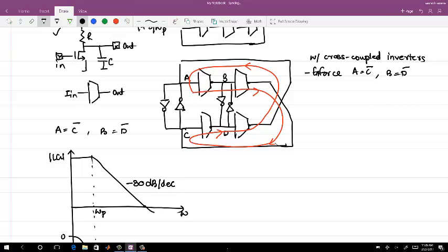This is what I am trying to enforce. Okay, this is just a very top-level picture, which helps me understand that if this relationship is enforced, then this particular oscillator will oscillate. Okay, but this is still not talking of the Barkhausen criterion, but that has to be satisfied. So what else can you think this inverter is doing?